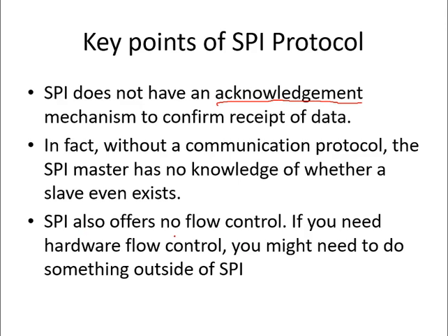SPI also offers no flow control. If you need hardware flow control, you might need to do something outside of SPI. Means whether they are having synchronization with each other or not, to control that, you don't have anything in SPI. Okay, so these are some drawbacks of SPI: no acknowledgement, no flow control.